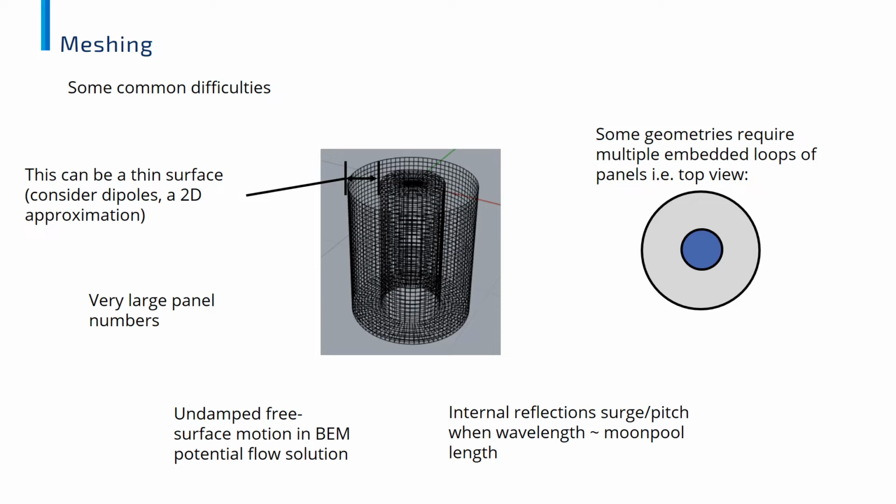So you may find that even when following the recommended modeling methods, it's very difficult to get good quality boundary element method results for an oscillating water column type device. A number of reasons for that are shown on this slide here. Basically, it's very difficult numerically for a potential flow type solver to resolve all of these issues.